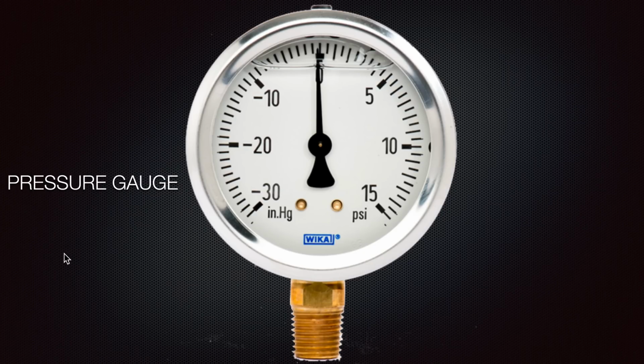Pressure gauges: calibrate your pressure gauges frequently. Some good companies have a really nice management system with the exact time for each calibration of the pressure gauges, so you are able to check them frequently. It can be every 3 months, every 6 months, or once per year.